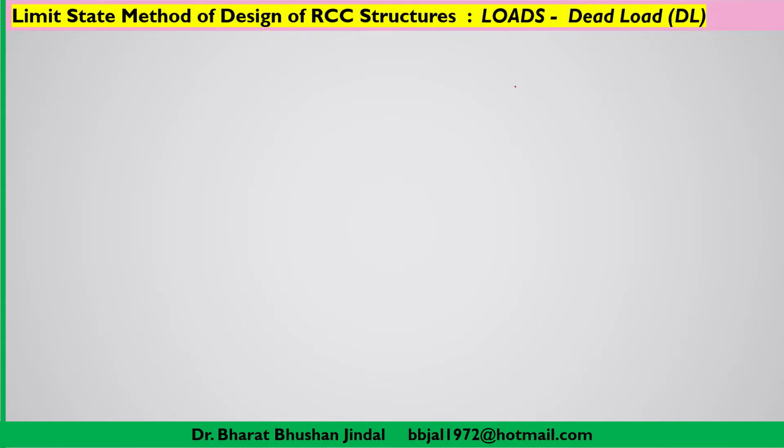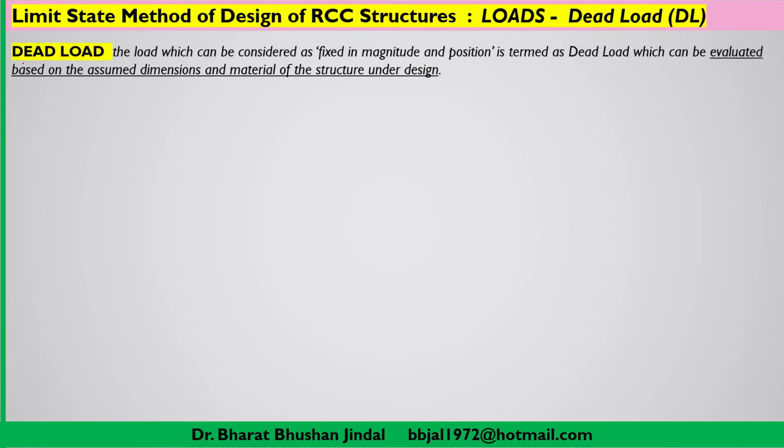Now, in the limit state design method, that means loads. First of all, we will be discussing what is the dead load. So now let us go through the information. Dead load is the load which can be considered as fixed in magnitude and position, and that type of load will be termed as dead load. And this dead load you can assume based on the assumed dimension.